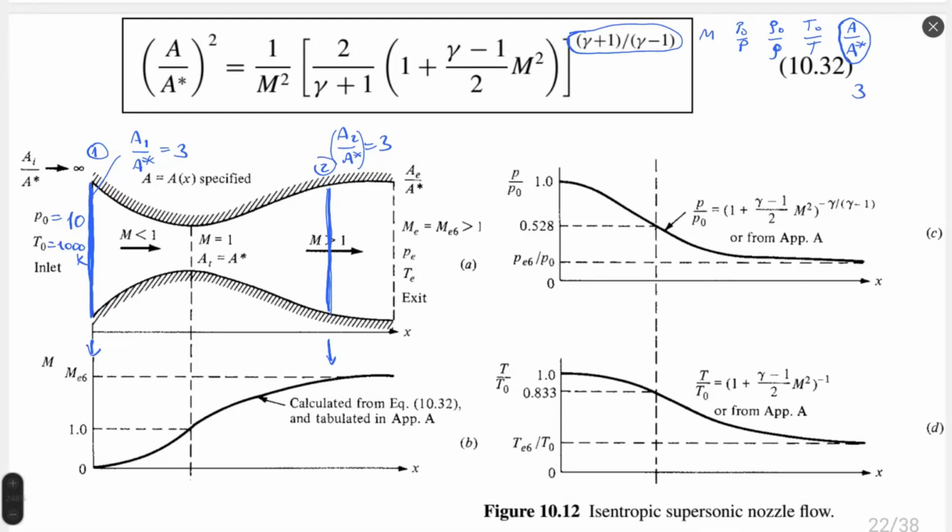I will see Mach number corresponds to 0.2 in the table. And the density I will not need, and pressure is 1.028. Sorry, temperature 1.008 and pressure 1.028. I will not calculate density.